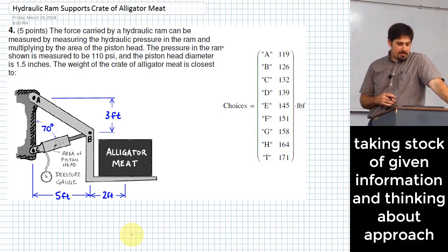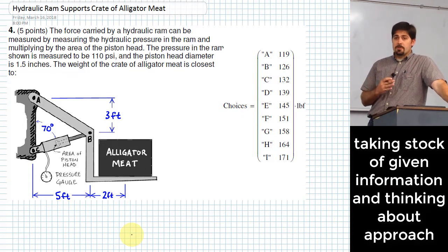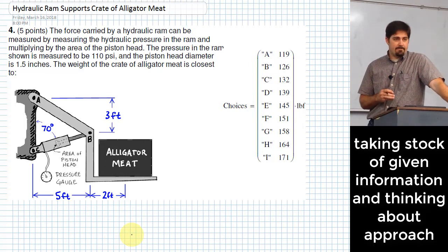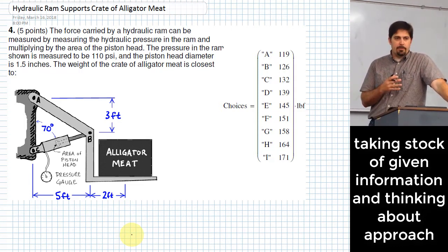We also need to do sort of the statics part of the problem, which involves doing what, you think? Okay, we probably will at some point need to sum some moments. Before we sum moments, what's the step we should do before that? A free body diagram, right? Summing moments is doing an equilibrium equation. That equilibrium equation arises from the free body diagram that we draw for this system.